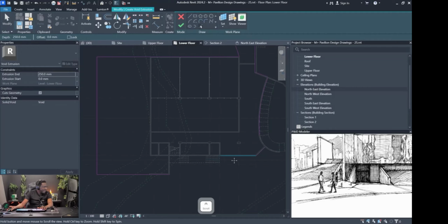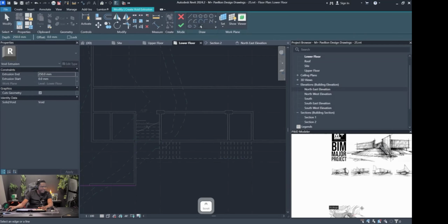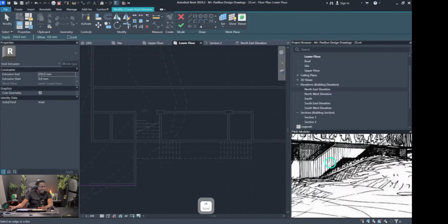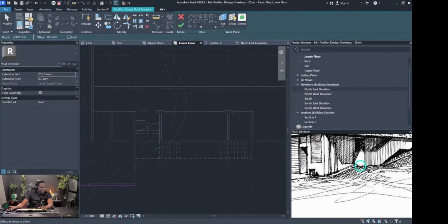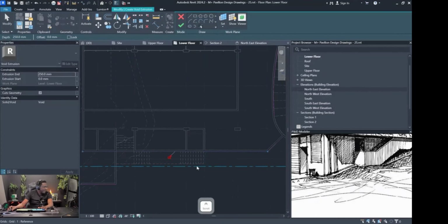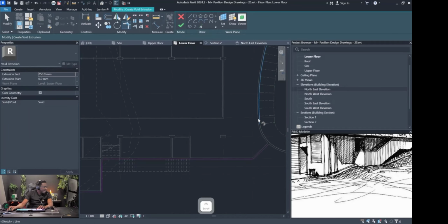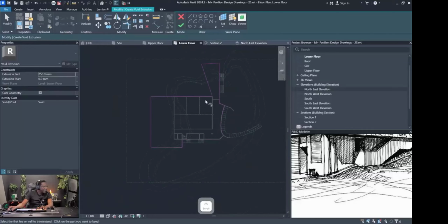And then the rest of it is, this terrain goes underneath the stairs. This part is a little tricky. If you can see here, the terrain really goes right up to the wall below the stairs. Right. And then this wall here is this wall. So it should go right up to this wall. And then this wall. So we're going to trim this like that. Trim this. We need to pick line to pick this wall. And then trim this here. Alright, so this is what we need to cut.